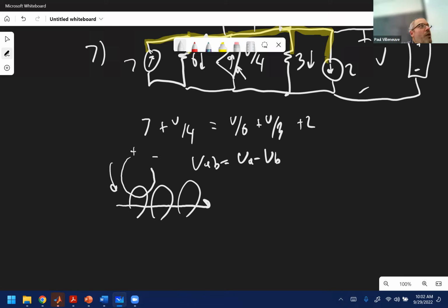But that only works if the current is changing or the flux is changing, which means the current has to change. So with DC over time, this is just going to reach steady state, and that current will be equal to 0. But if you take a look at Hall effect, it works on a very different principle. So now you can get clamp-on meters that will work very well for AC and DC. And so you can go buy a Fluke clamp-on for, I think it's $80.